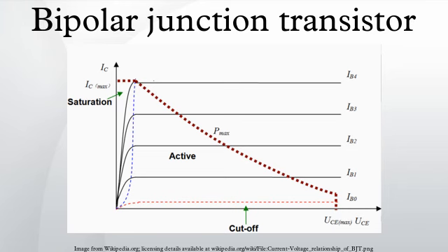The doped silicon has a negative temperature coefficient, meaning that it conducts more current at higher temperatures. Thus, the hottest part of the die conducts the most current, causing its conductivity to increase, which then causes it to become progressively hotter again, until the device fails internally. The thermal runaway process associated with secondary breakdown, once triggered, occurs almost instantly and may catastrophically damage the transistor package.